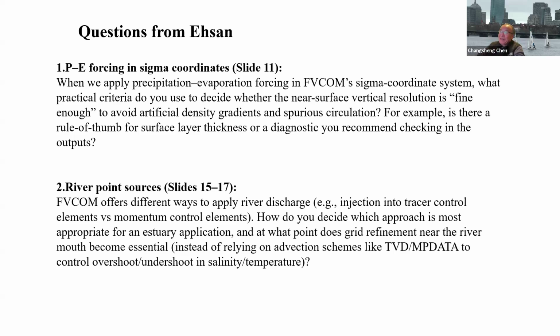Don't use the node. It can cause the eddy circulation around there. Because with the node method, they put the water in, it goes to the continuity equation first, then goes to momentum. But with the edge method, they put the water directly into momentum as a flux. So then the velocity changes first. Then after the velocity changes, the sea level changes. So when the resolution becomes really high, the two methods merge together. Okay, but the real problem is that the two methods differ when the resolution is coarse.